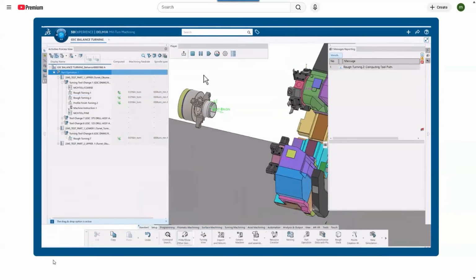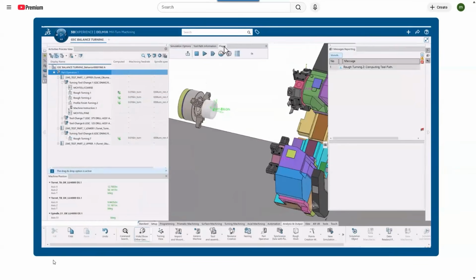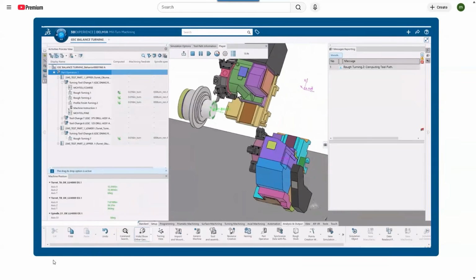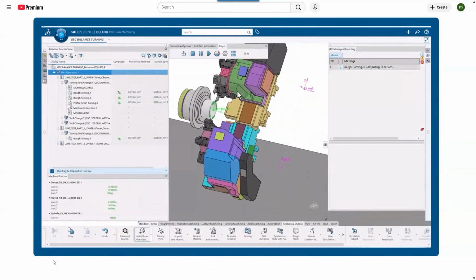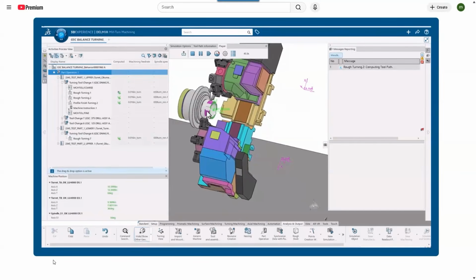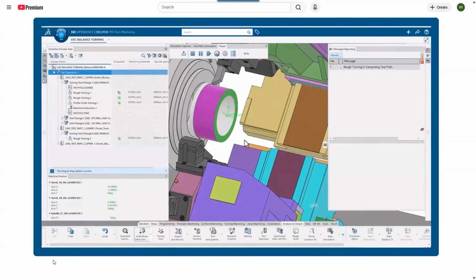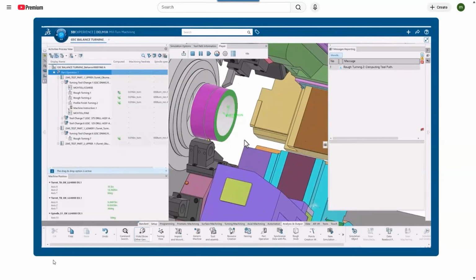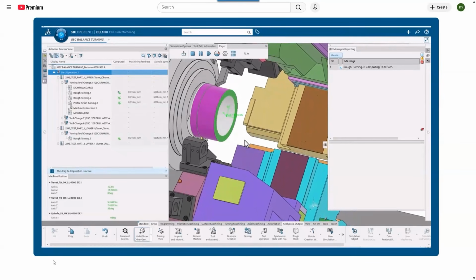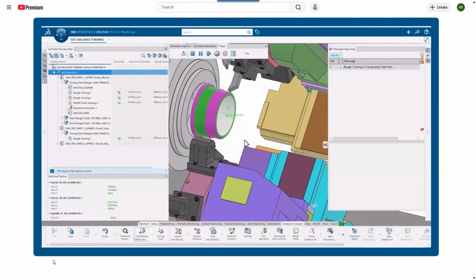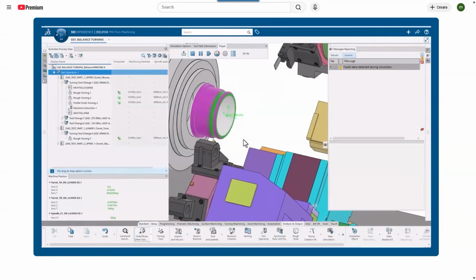Okay. When we go through and start running this, we are machining, just like you saw with SolidWorks CAM Pro on a single spindle, single turret. Here, we're invoking everything together and then checking for collision. We're facing with the top turret, and then we're doing pinch turning here on the bottom. Once we have that, we have the ability to move things out of the way and sync. If we had a sub spindle come up, we can program that movement of the sub spindle. The key here is we're not doing the black box post processor thing, where there's a black box at the end and you just hope that the G code comes out correct. What you see is what you get. How it behaves here is how it's going to behave in the machine.